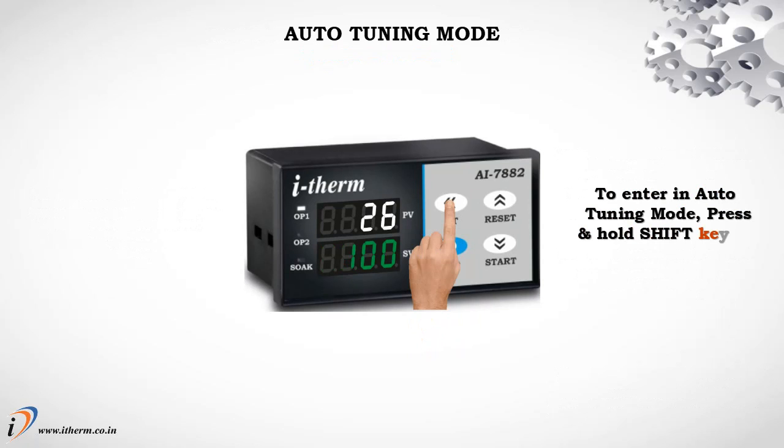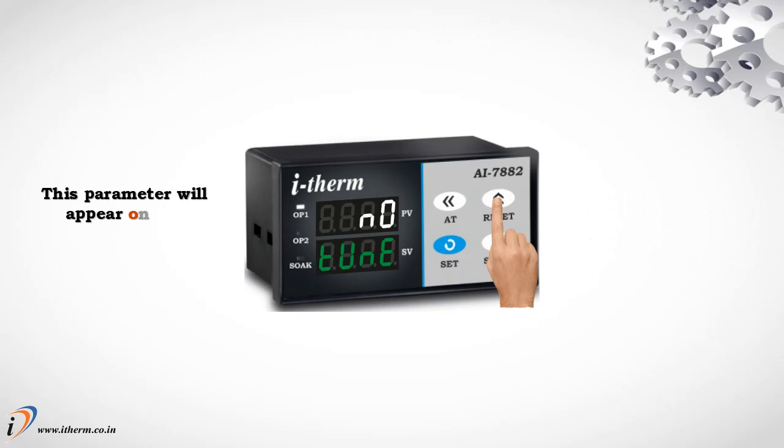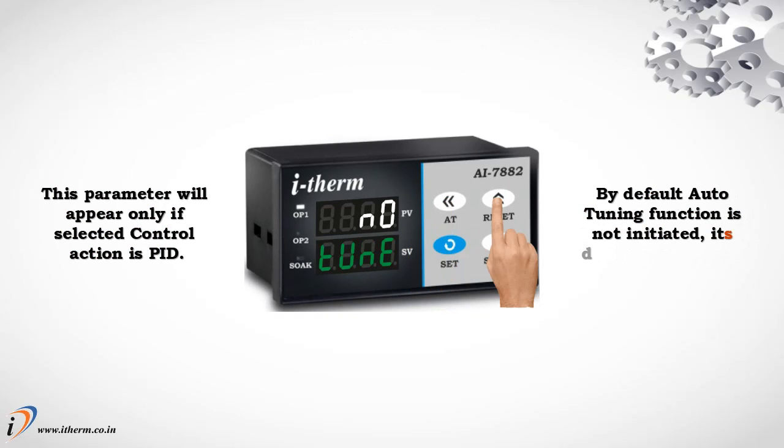Auto-tuning mode. To enter auto-tuning mode, press and hold the Shift key for a minimum of 3 seconds. This parameter will appear only if the selected control action is PID. By default, the auto-tuning function is not initiated. Its default value is no.